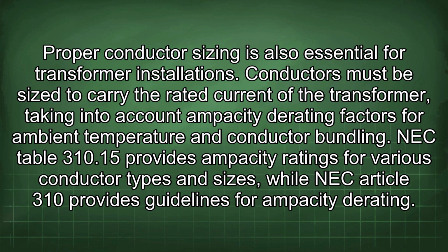Conductors must be sized to carry the rated current of the transformer, taking into account ampacity derating factors for ambient temperature and conductor bundling. NEC Table 310.15 provides ampacity ratings for various conductor types and sizes, while NEC Article 310 provides guidelines for ampacity derating.